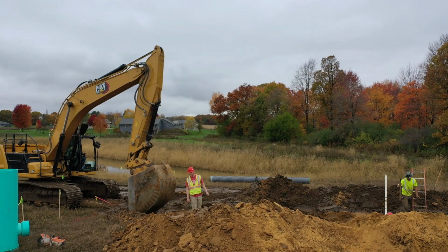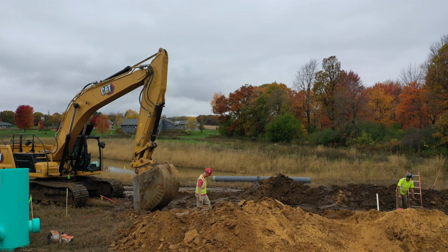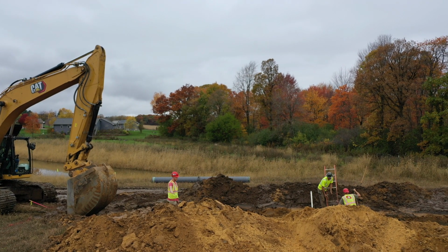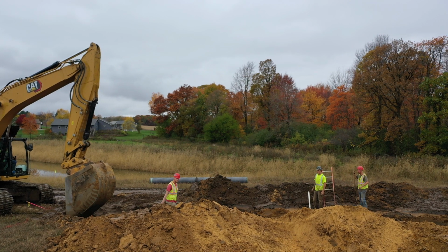Obstacles. Check the location of buried pipelines, gas lines, or other buried utilities or material. Do not obstruct your vision when traveling or working. Carry the blade in a low position for the maximum visibility.